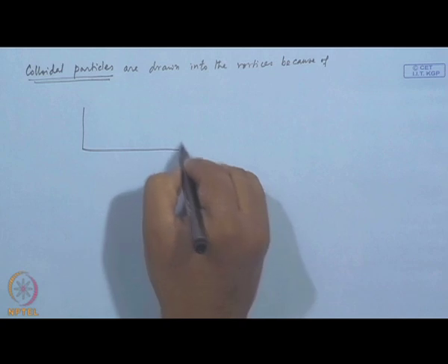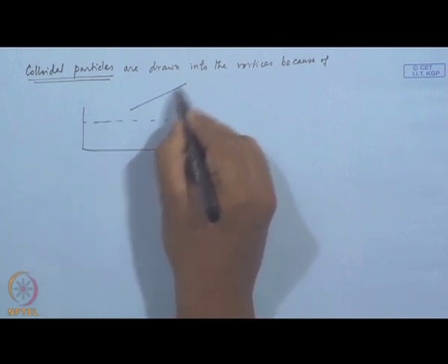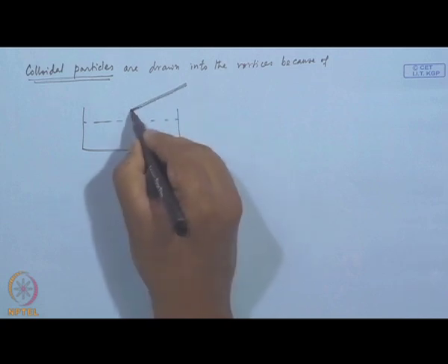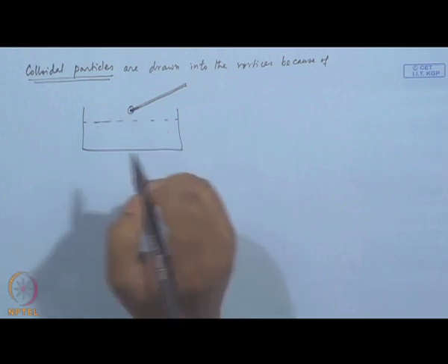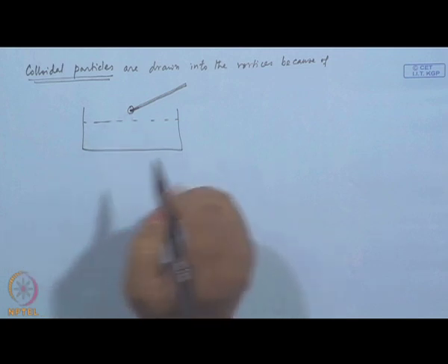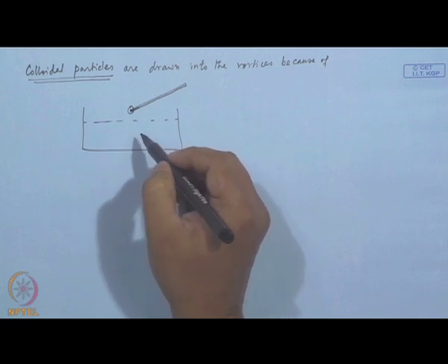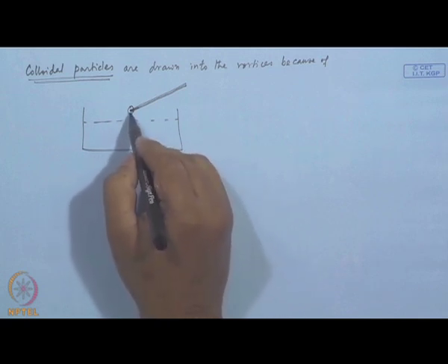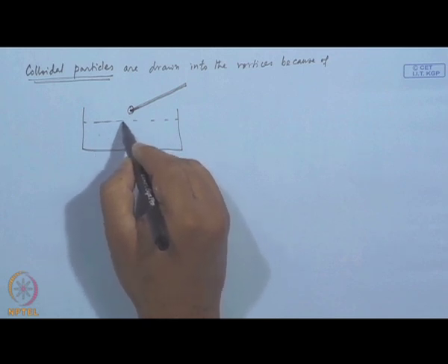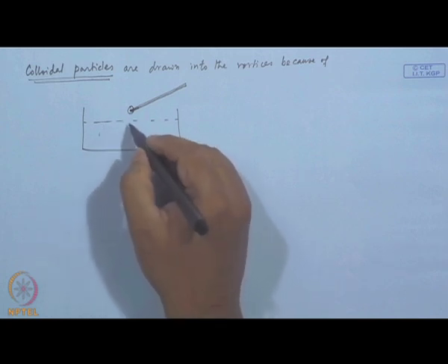What we are talking about here is that this is the liquid pool inside the cavity, and the electrode is brought in here, a tip electrode, this is called corona electrode, a very sharp tip at a very high voltage. So, that is brought in here, and this distance is small. So, here near the interface, the colloidal particles will be pulled by DEP force, closest to the corona electrode tip.